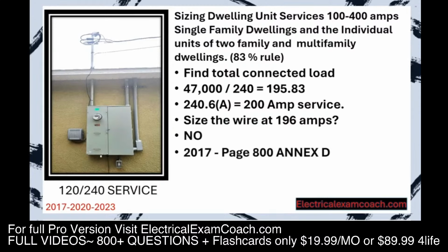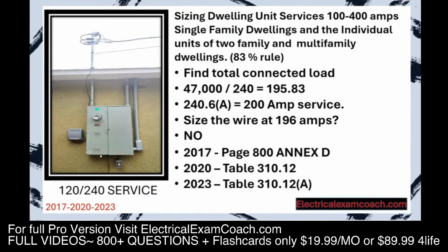Let's all head to page 800 if you're in the 2017, this table if you're in the 2020, and this table if you're in the 2023. This is technically called the 83% rule, but I'm not going to force you to do the longhand math. I'm going to take you to these tables that are in the NEC that are almost like a cheat sheet that makes this super easy to apply and understand.